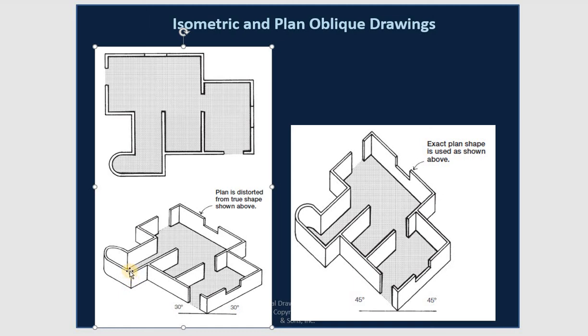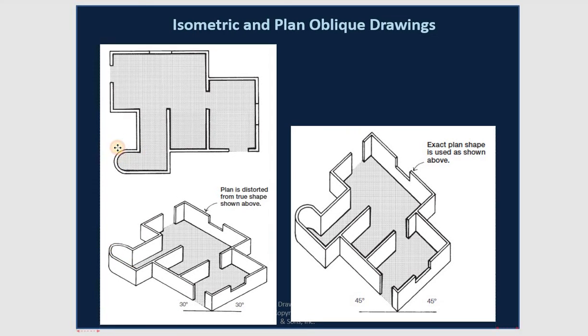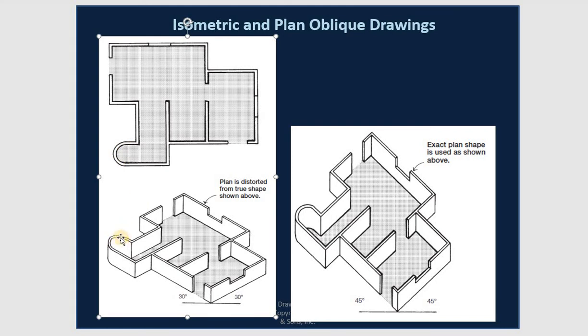High up 4 feet. After that, you draw another line for the high elevation from the wall. After that, this is the curve, so you draw the curve. Okay, and continue with this one that is behind, so you can go like this behind. Okay, so you go everywhere like this. That's the isometric 30-30. If you change, you need to do 45-45 isometric, but the angle is bigger, and you can do this one 45-45, and you can see more of the interior of the building.